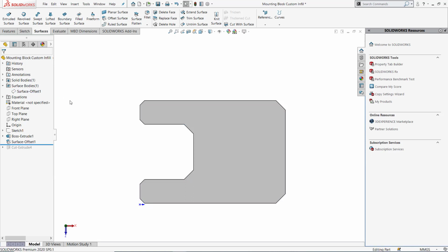Now, we have the ability to get started actually creating that infill pattern. The process that we'll be using in order to create this infill pattern is first, I'm going to sketch out an individual region where I would like this infill to be placed. I'll then sketch the patterns out individually, merge them back together as one solid body, and then add any of the auxiliary features back into place.